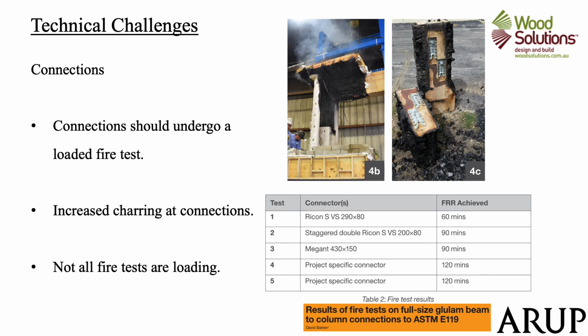Connections, so the weak point of the structure. Any exposed timber connection should undergo a loaded fire test. Connections are difficult, nigh impossible, to determine the fire resistance of analytically, so full-scale fire tests should be used. Not all connection tests are loaded, which I don't really see as compatible with use in the building.